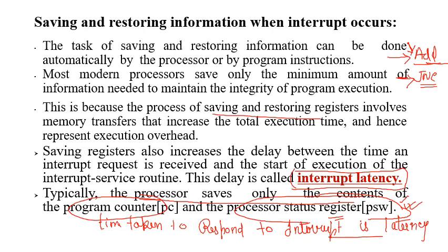Now if it is jump if no carry, if this instruction has to be executed, then the previous program status word has to be saved, because after the interrupt it goes to the service routine, right? In the service routine, there will be add instructions, subtract instructions, and some other instructions which affect the program status word. So when it returns back, the program status word you have currently is different from the previous program status word before the interrupt occurred.